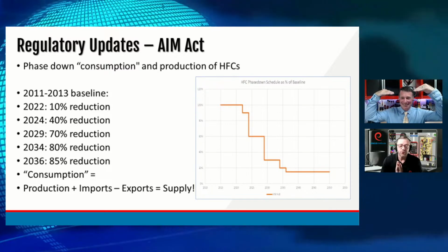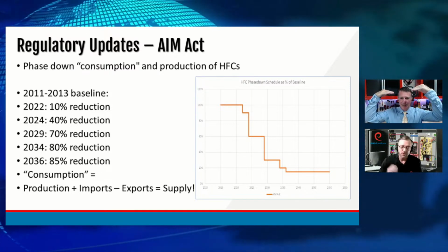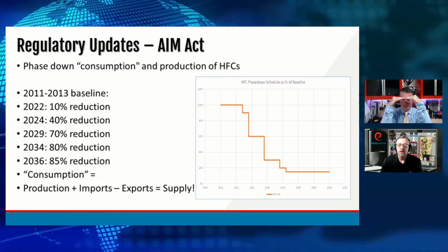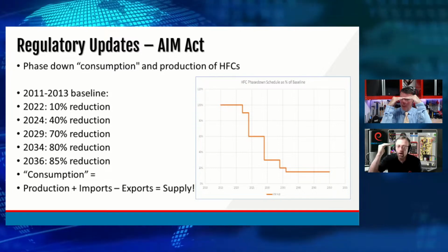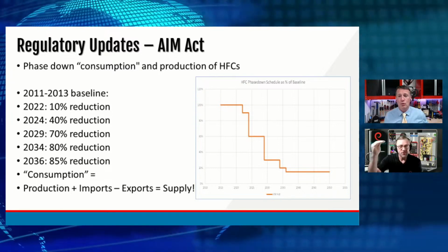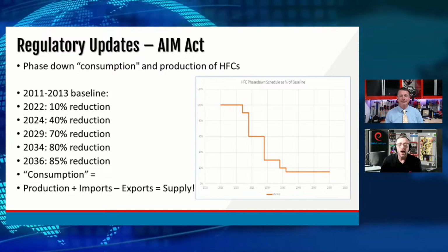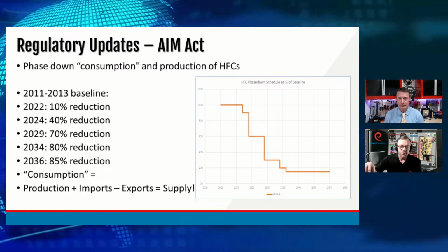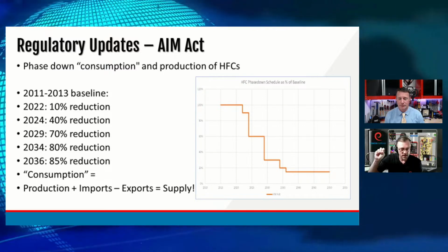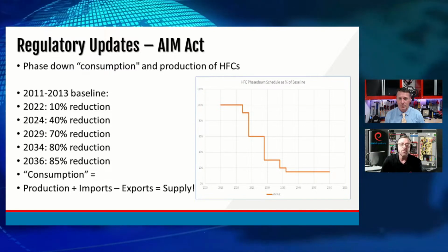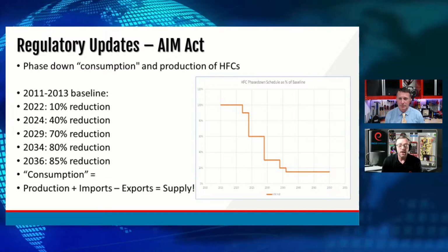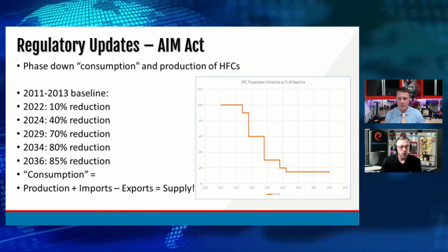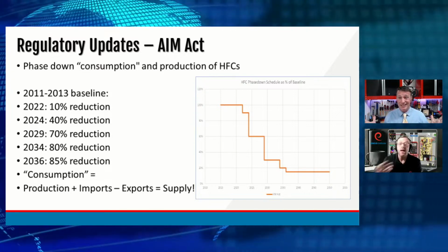That's right. If I'm a refrigerant manufacturer, I get my allotment from the government, the EPA. It says, get my little chunk, I can make 1 million pounds. Based on pounds? Based on carbon emissions, based on the GWP. So as the manufacturer, I get to decide what I'm going to make, but each tank of refrigerant I make draws from those credits. It's going to deduct from my bank account. So if I want to make enough refrigerant to sell all year, I'm going to probably pick the lower GWP ones, so I can make more tanks of it.